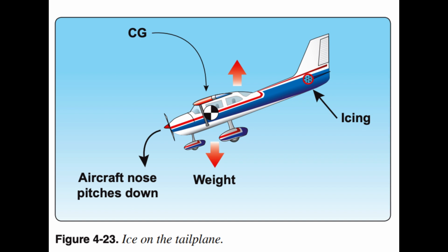Another system uses a bar at the lower end of the windshield to spray de-icing fluid onto it and prevent ice from forming. On high-performance aircraft that require complex windshields to protect against bird strikes and withstand pressurization loads, the heating element often is a layer of conductive film or thin wire strands through which electric current is run to heat the windshield and prevent ice from forming.